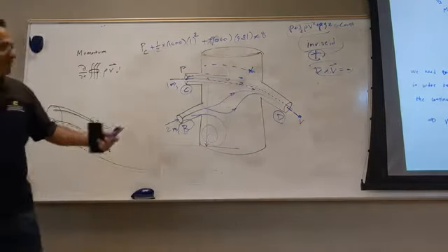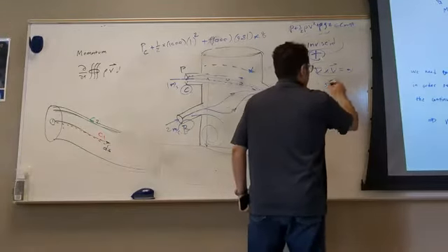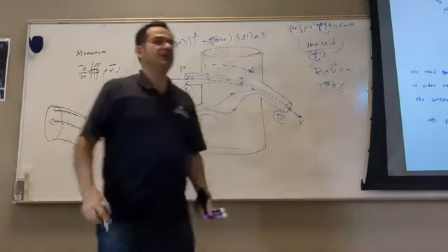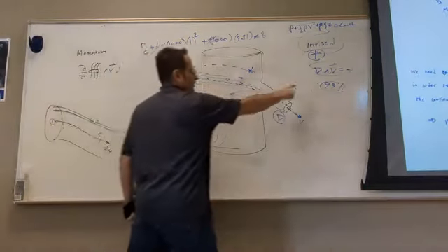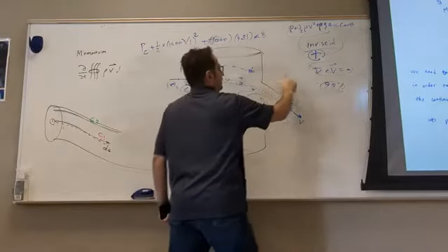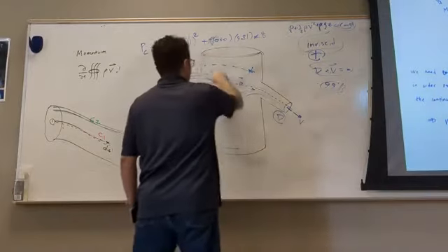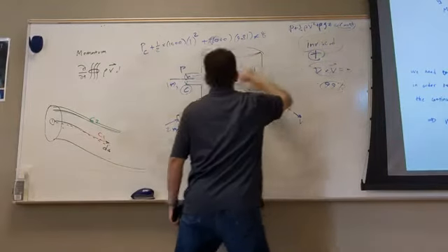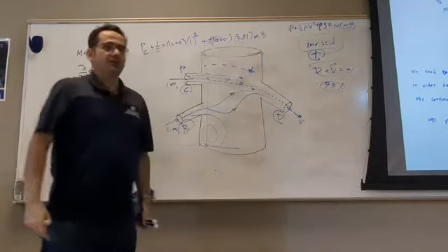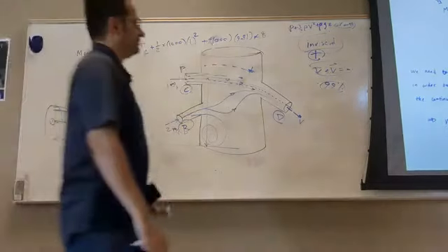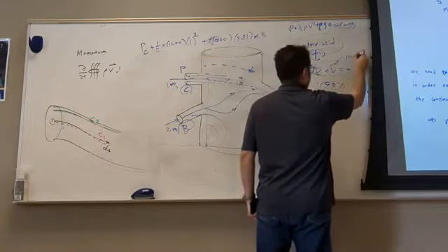Now look, this irrotational assumption, as I mentioned, 99% in engineering they make this assumption when they design things. Because of this assumption, now the constant of Bernoulli is the same for the entire flow. That means this head, this sum, is equal to here, is equal to here, is equal to here, is equal to here. But you see that it's just an approximation because you assume that the flow is irrotational.